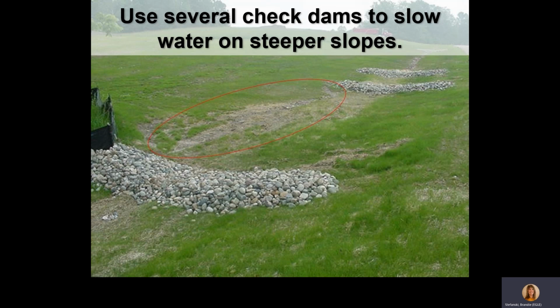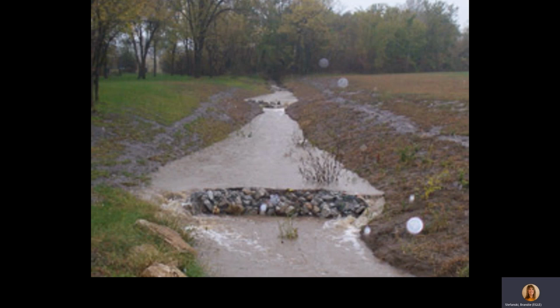It's difficult to see, but there's some side cutting. Look at the middle check dam. The sides were either not brought up enough or it was not centered. This series of dams have good spacing, but the stones should be carried up the side slopes more. The middle should be lower to allow water to cascade down the rock.